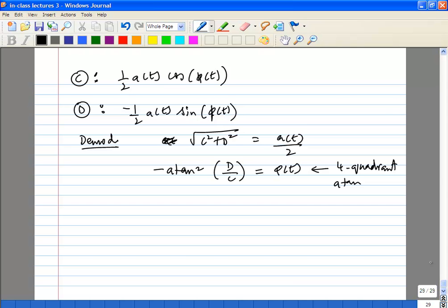So then what you can do is, once you have the baseband signal, you can perform channel selection. Remember, you did band selection up front, you have received the full band, it's come down to the baseband.